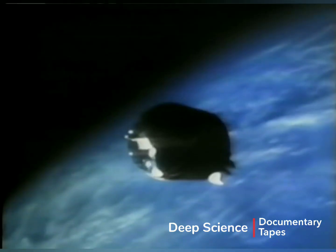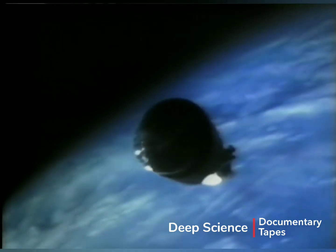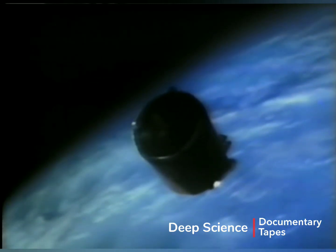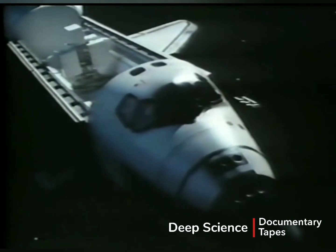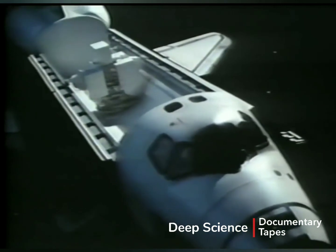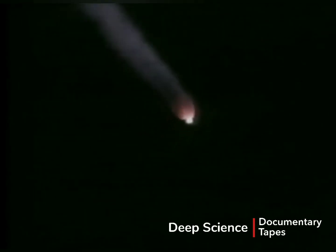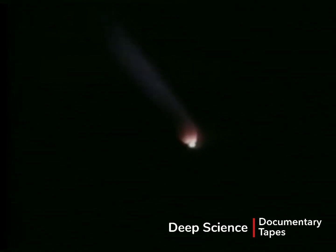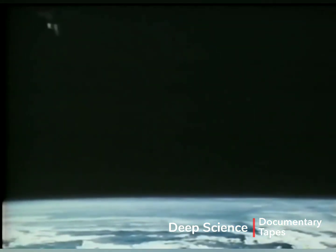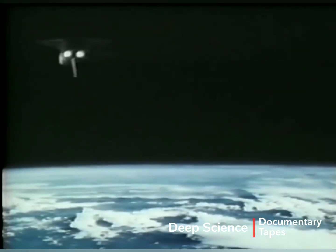This is particularly true for spacecraft orbiting at very low altitudes, where the effects of atmospheric drag are greater and, if not compensated for, will eventually cause the spacecraft to deorbit. A spacecraft's operational lifetime is frequently limited only by the amount of fuel available to maintain its desired orbit. When its useful life is complete, a satellite is left in orbit or is deorbited, burning up when re-entering the Earth's atmosphere.